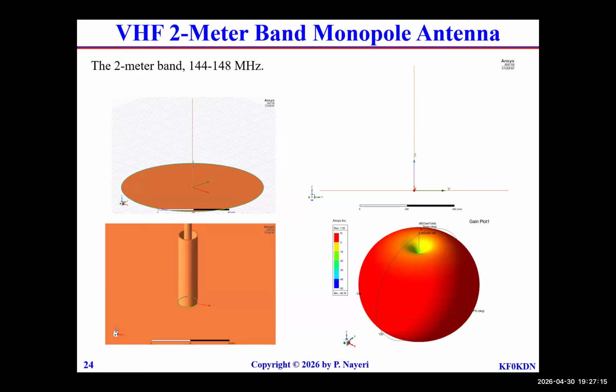Theoretically, an ideal monopole would have a pattern like this, nothing below the ground plane. And if the ground plane is finite, then you would get fringing fields here. But this ground plane is so small that basically the field completely wraps around it. So then is the impedance preserved from the dipole condition into the monopole condition? Very good. Ideally, the impedance of the monopole is half this. But this is under the condition that image theory perfectly applies, which means an infinite ground. In this case, and you can do this study for sure, as the ground plane is reduced in size, the input impedance changes so much, it becomes so small, you can't even match it anymore.